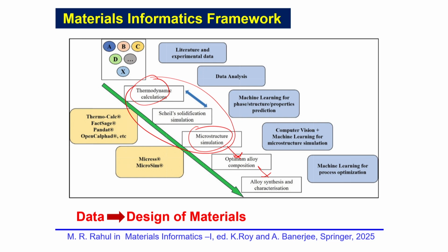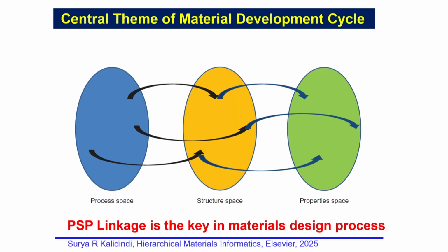There are many software packages available like Thermo-Calc, FactSage, Pandat, OpenCalphad, all of which allow you to do thermodynamic calculations. These are nowadays routinely used. You can also do microstructural simulation using MICRESS or MicroSim. These are all software which have been built up. So, these allow us to go from the top to bottom. The idea is how to connect data with design of materials. That is the key aspect in these things.